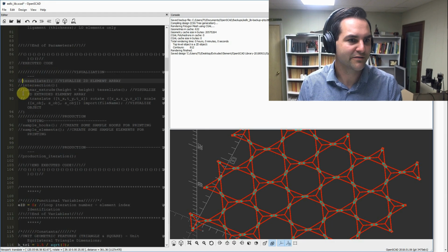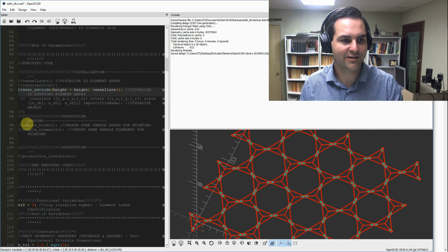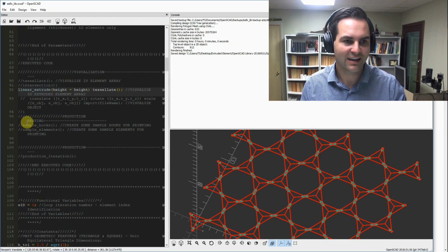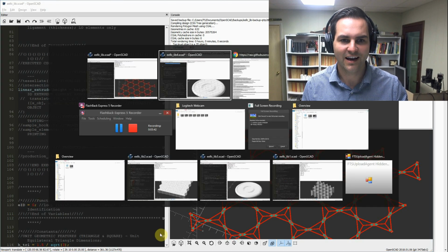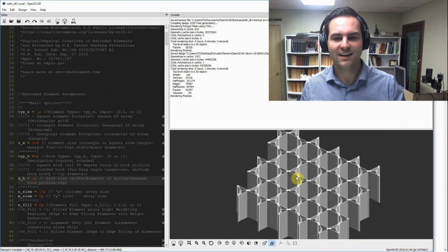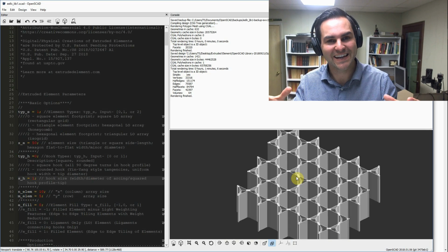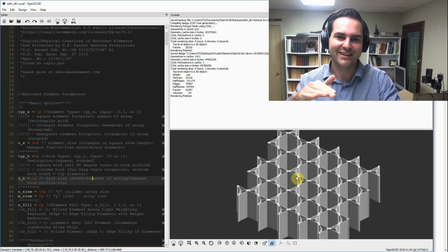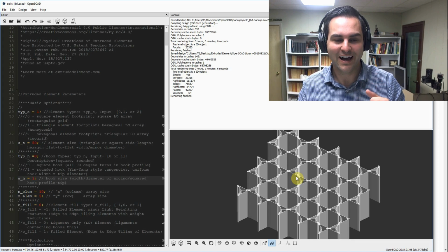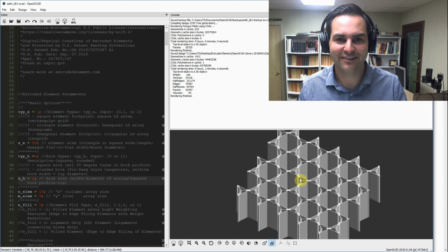And you'll be instructed to then comment out the lines, here it says 90 lines down. It could be one off or so. Comment that out with 2 backslashes. And if you want to bring them into the third dimension, just uncomment and press F6. F6 is the magic key here. And I'm switching between OpenSCAD instances because recording my screen and generating 3D extruded elements probably will have a fault with the video or the extrusion rendering.